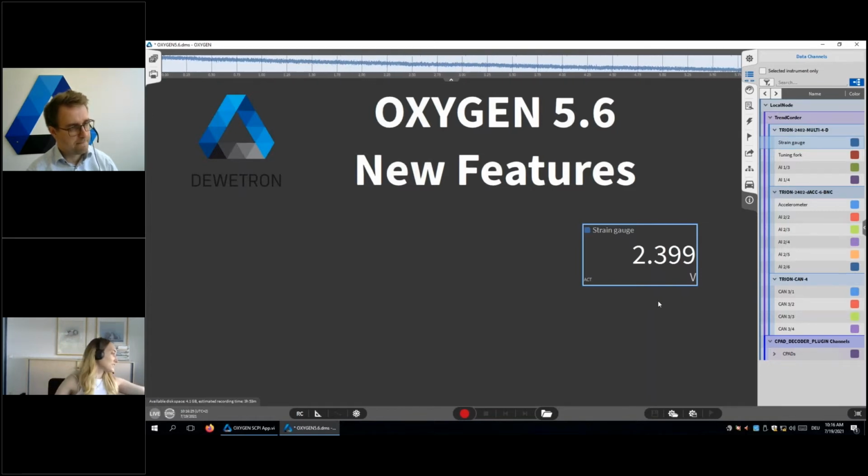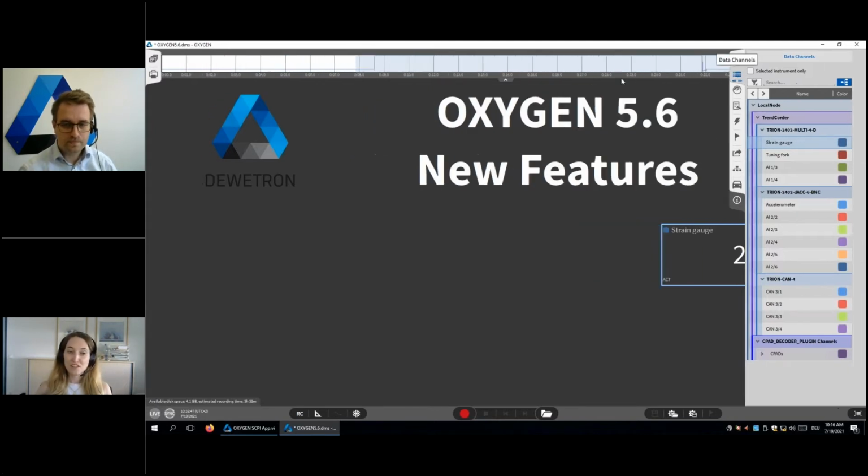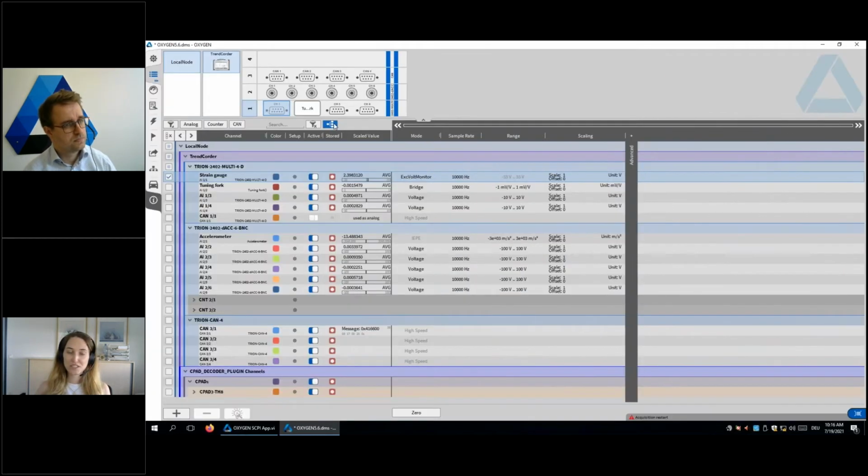If it is not connected correctly, we measure the compliance voltage. So we know the sensor is not connected correctly. There's something on the wire, some problem, and we can go check it. And if we connect it correctly again, we can measure the voltage drop. Okay, so that is the mode to see if the sensors are connected correctly.